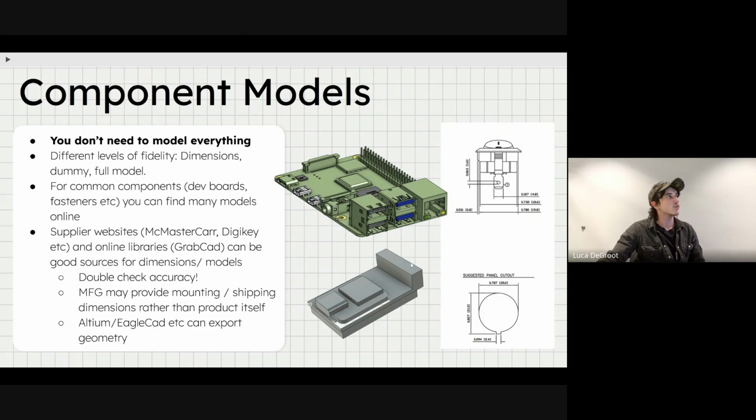So I wanted the overall thickness. I wanted to make sure that the connector port that I would actually have to connect something through was modeled. And sometimes it's just literally a cube with maybe a port sticking out so that I can reference that later. Sometimes it's a little more complicated than that, but often I'll just make a block, and that's like my dummy model. And it's the bare minimum of dimensions.